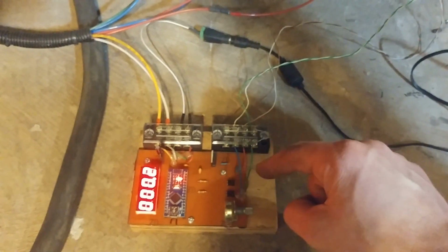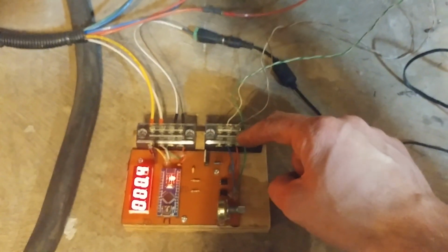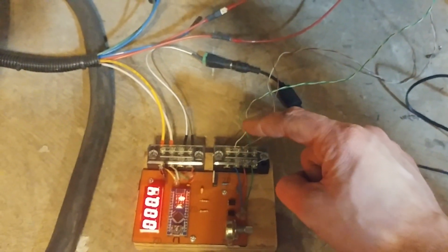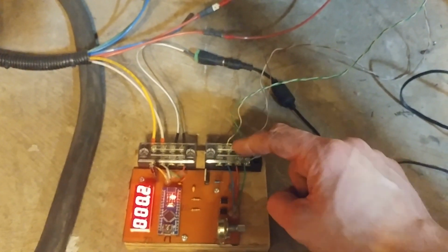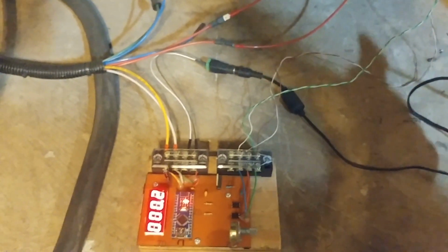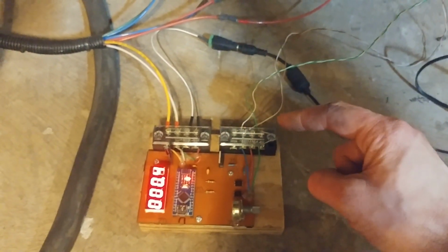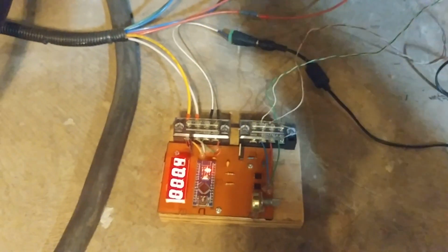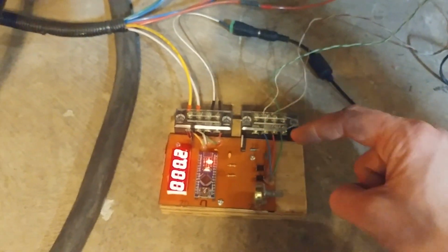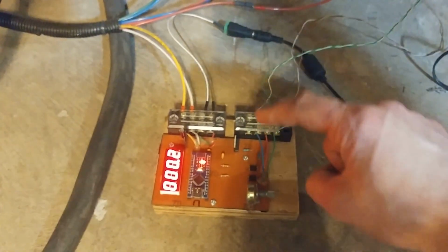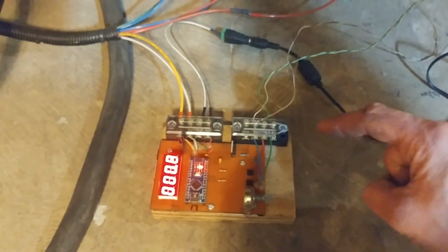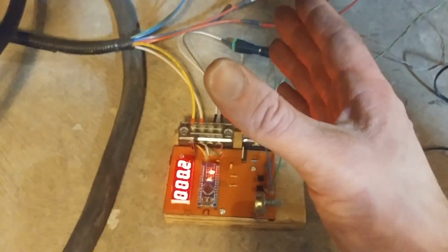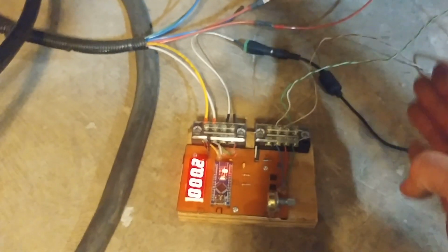And these wires then come to this screw terminal block where we've got a solid green, a solid brown, a white and green, and a white and brown. And the solid green and the solid brown come together on this one here, and then it goes back to the ground on the parallel port breakout board. And then the white and green and the white and brown each go to pin 12 and 13. I actually forget which is which, it's not terribly important, but they go to each of them. So basically when you activate an opto-isolator, it will then take that respective pin and draw it through to ground. All of this is coming through this side here without the signal ever having to come back on this side of the board. So it keeps it all cleanly separated, that and that.